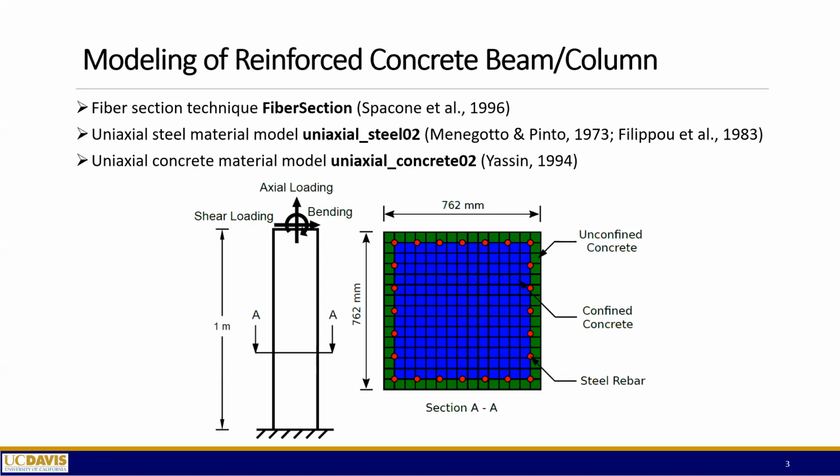If I may say so, the confined concrete is inside the hoop reinforcement, and that is the one that is confined, and this is much stronger concrete. The one that's outside is outside of this longitudinal and hoop reinforcement. More important is the actual hoop reinforcement. The unconfined concrete is much weaker, but it's okay to model it, though it's eventually going to flake off.